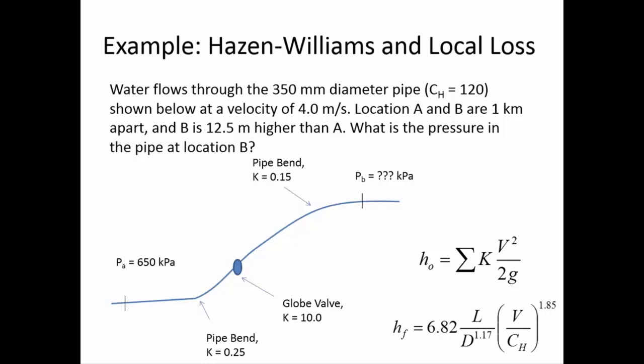There's no turbine, and the turbine has to be on the right side of the energy equation when our notation is that water flows from 1 towards 2. Since there's a direction assumption in the energy equation, that's why we put the pump term on the left side and the turbine term on the right. There's no turbine either, at least in this example.